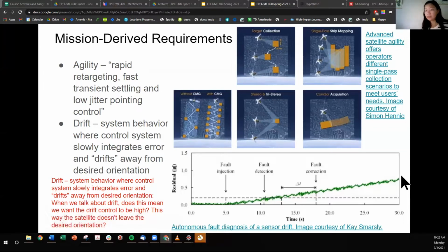You can correct for this drift by trusting an independent reference cue, with an independent measurement coming from, say, a star tracker. A star tracker differs from IMU in that star trackers lock on to a measurement provided by the celestial sphere, which is constant and steady.